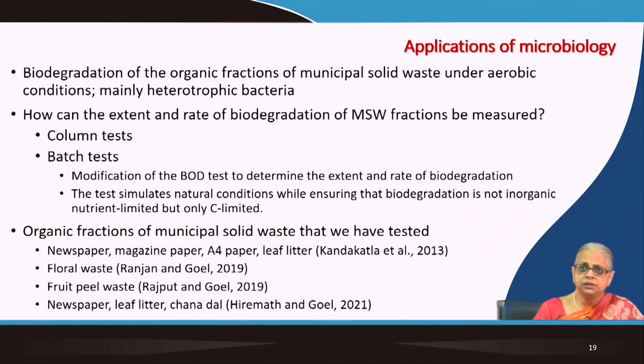So the question that we're trying to answer in these tests is, how can we measure the extent and rate of biodegradation of the organic fractions of municipal solid waste? Now, what I did not mention in the previous talk about the BOD test is that with the kind of data that I showed you, you can come up with the reaction rate constants, which are very important when you're designing treatment processes, because the design is based on our understanding of the reaction kinetics.